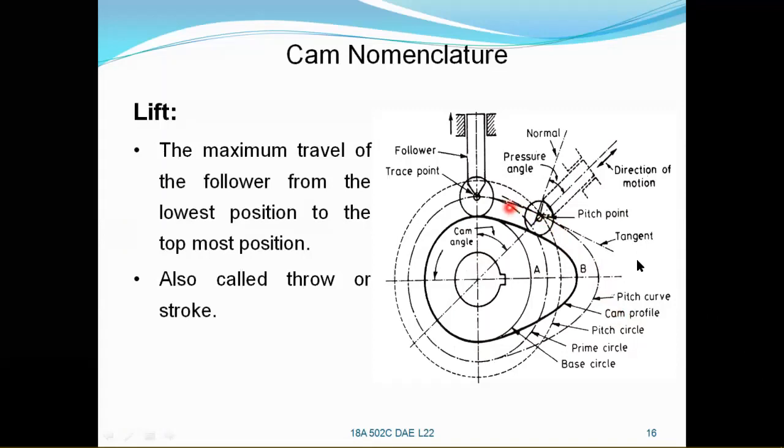And pitch curve is the path traced by the trace point for the cam profile, and the pitch point is a point on the pitch curve at which the pressure angle is maximum, and the trace point is the reference point on the follower.